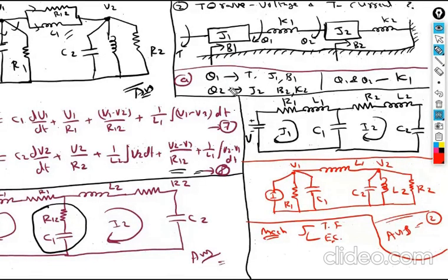Anyhow, two nodes based upon time factor in the examination. So for these 2 nodes, extract the common elements and unknown elements. After that write the 2 basic equations. So if it is translatory, then force equation. If it is rotational, then write the torque equation. After that you have to go for what? Converting those displacement x's or thetas to what? Velocity. How to convert, all of you are aware, dx by dt is equal to what? Velocity or angular velocity w.